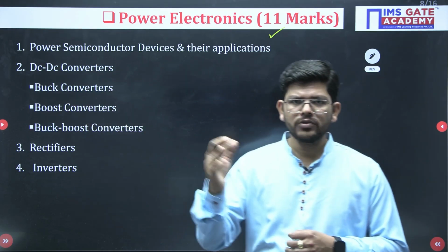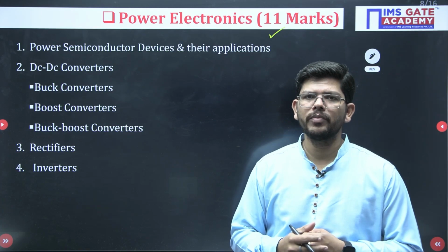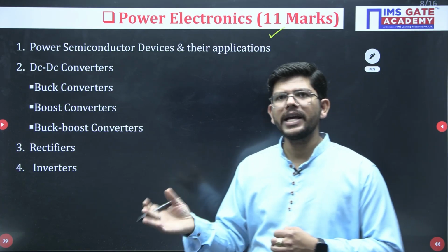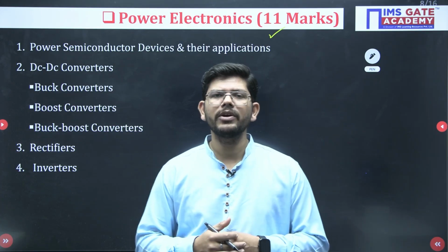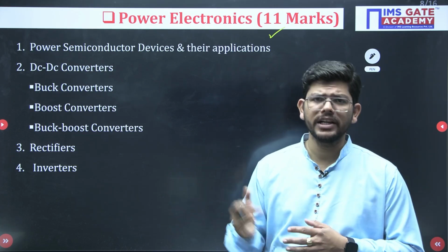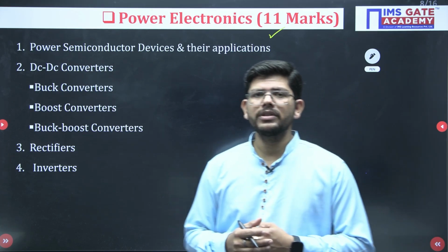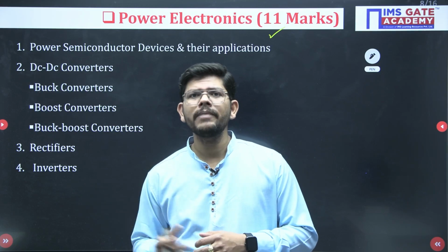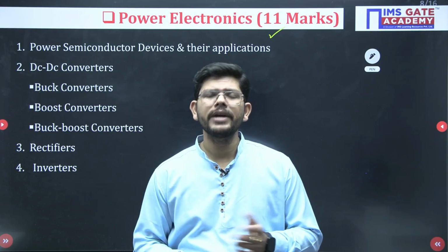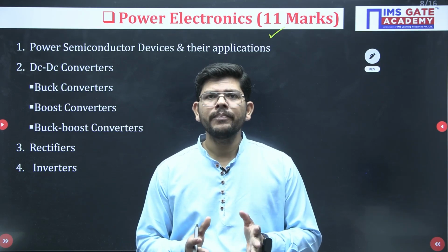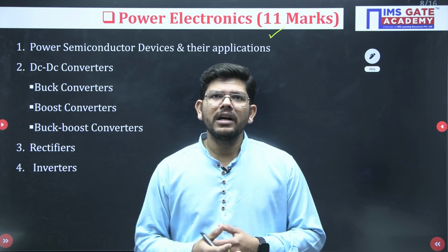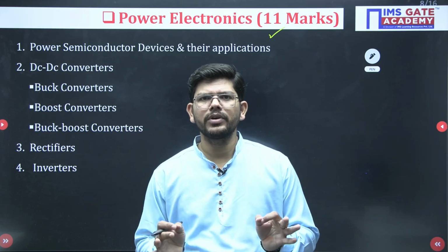Okay, all other switches are used for lower frequency operations. So MOSFET can give very high frequency operation. TRIAC is a switch which can give very low frequency operation. TRIAC is 4 quadrant, others are 1 or 2 quadrant devices. Okay, so their switch realization and their operating characteristic, this is important.